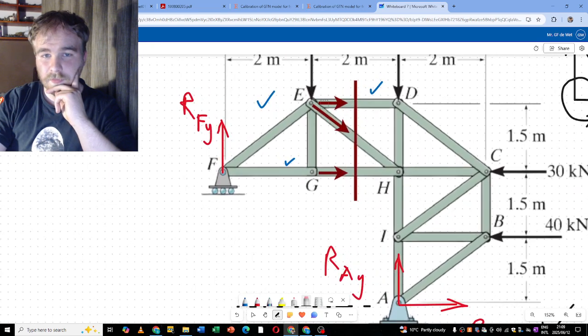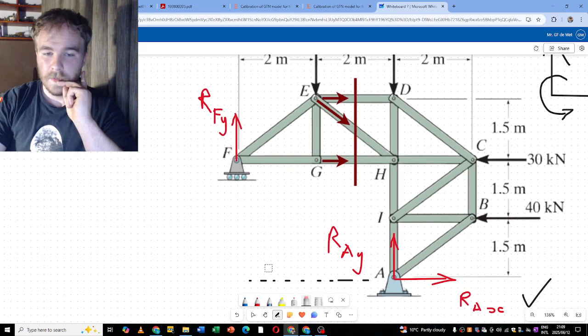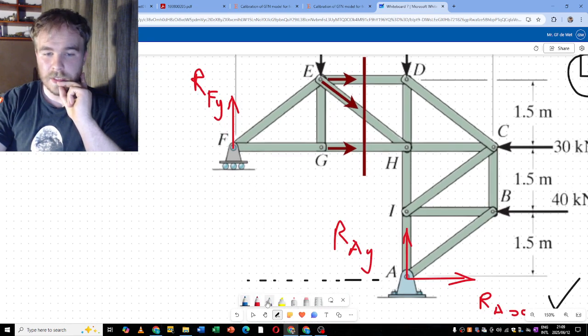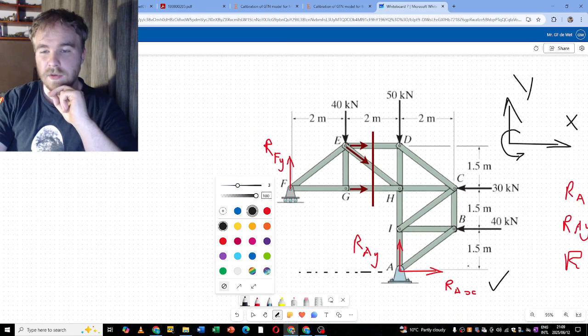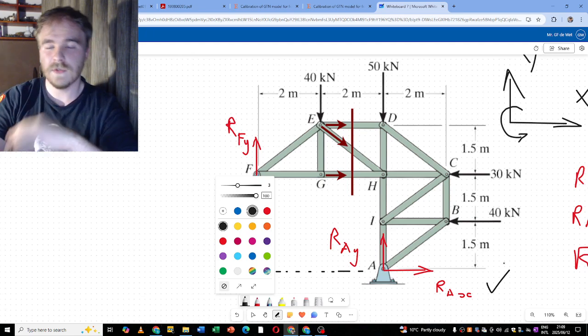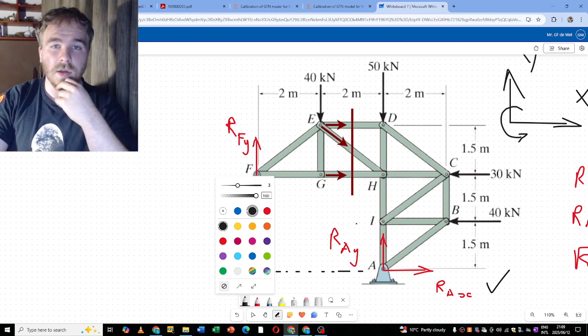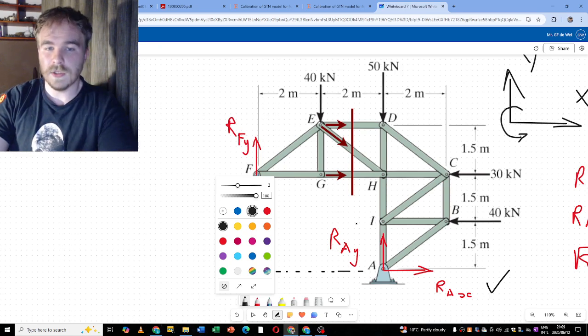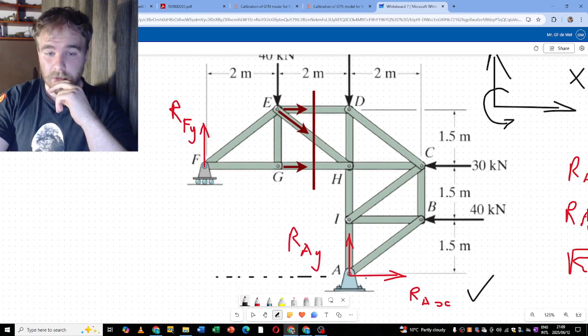So I'm going to have to make sure that I do not need to calculate more than 2 per equation that I set up. So I'm going to set them up in sequence, and I should not have to calculate more than 2 forces or 2 members' forces for each point that I'm looking at. Otherwise I can't solve that in one go. Then I have to do multiple equations and solve them simultaneously, and that gets really nasty really quickly. So I don't want to do that.